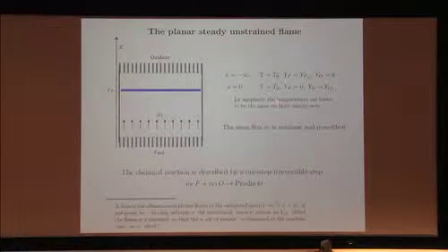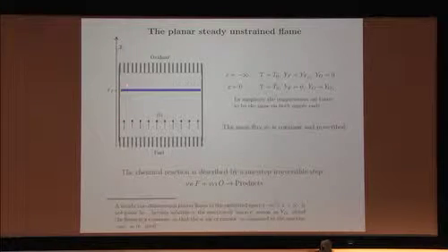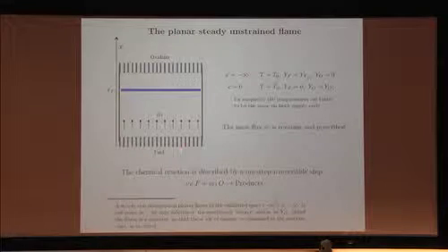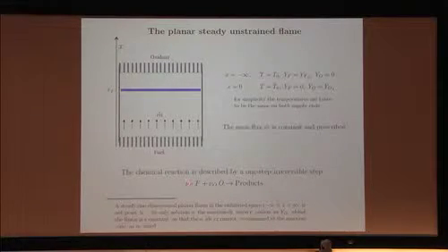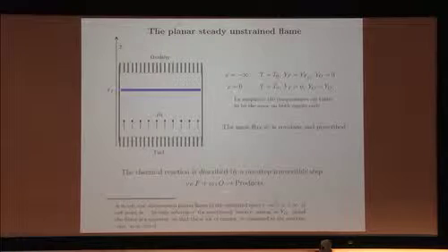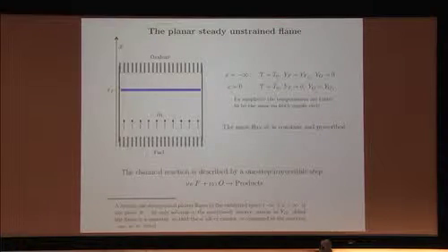So M is prescribed, and the problem that we are interested to solve is to find the location of the diffusion flame and the flame structure. And again, we're going to focus on a one-step overall reaction of the form fuel plus oxidizer go to product. Of course, for a diffusion flame, it's the simplest scheme that you can think of. You need both fuel and oxidizer.